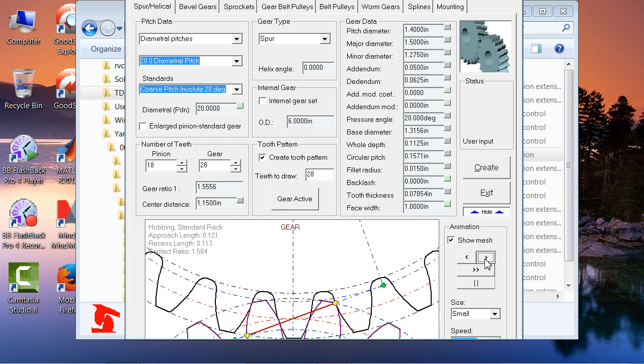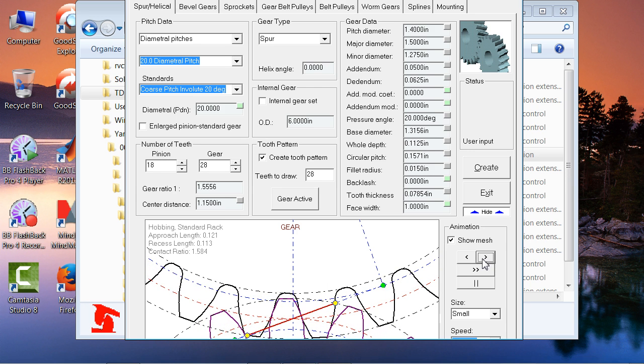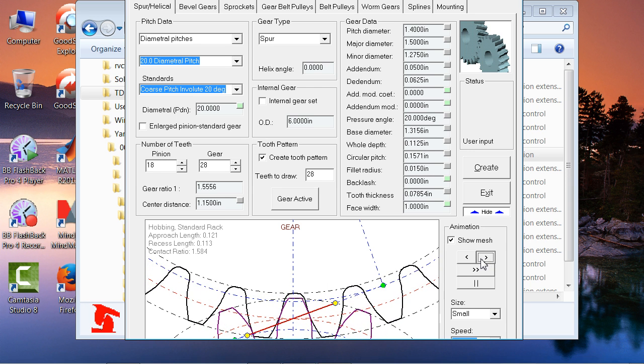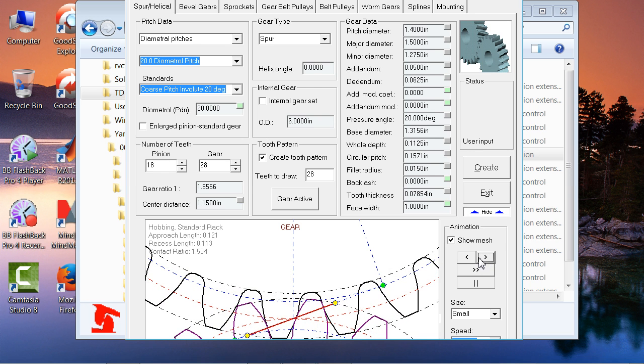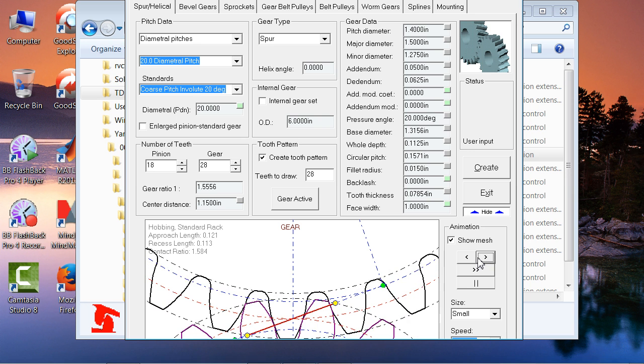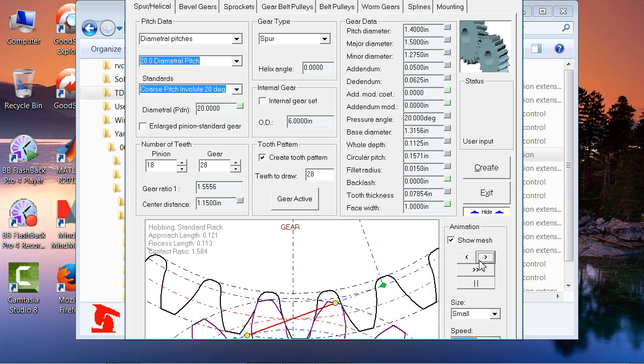If you observe carefully, the contact point between two teeth always moves along this straight line, the one indicated by the yellow and red dots. Right here they basically get away from each other. So the contact point is always along the same line of action. When you use the involute profile, that's the idea. Is that okay?